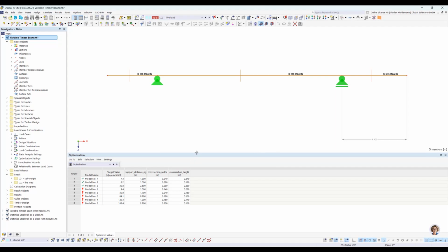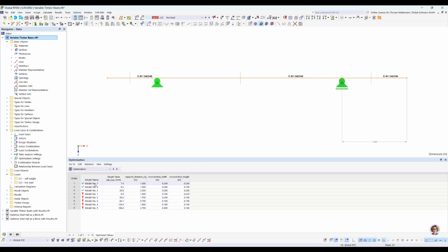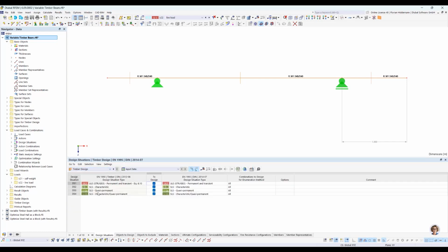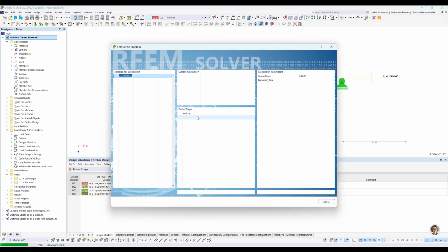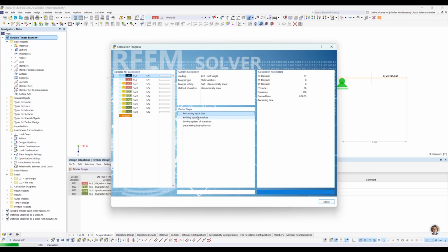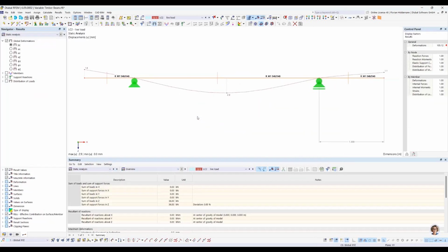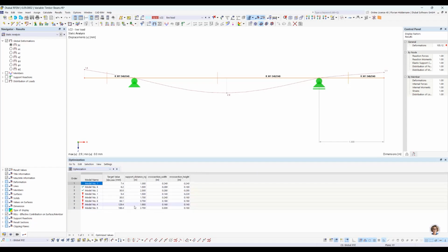So what you can see here, the calculations performed up to this point are stored. We have now 8 results. And as you can see here, the green checkmark means it's very important to see it again. This model is now active, and because I canceled the calculation run, the add-on doesn't calculate the last cycle. So if you jump into a new model in the list, you have to calculate the model itself. We store only the results you can see here in the list.